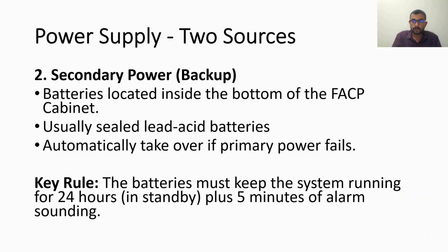Okay, so for 24 hours you will run it on batteries, you will check the voltage levels, and then after completing the entire day, the inspector will ask you to run the panel for at least 5 minutes. Five minutes means in the alarm condition, so you will have to activate one device, and the panel will keep on sounding the alarm for a continuous 5 minutes.